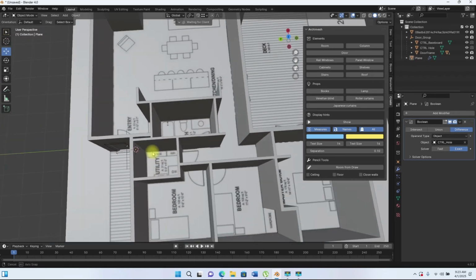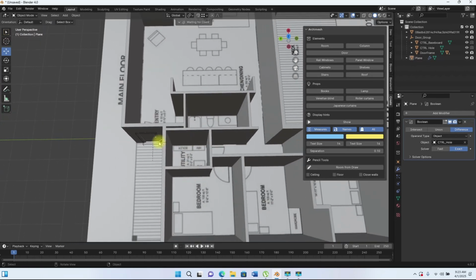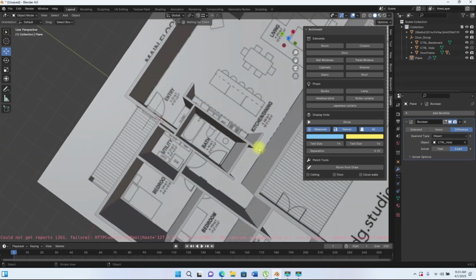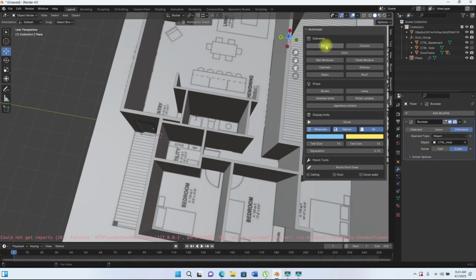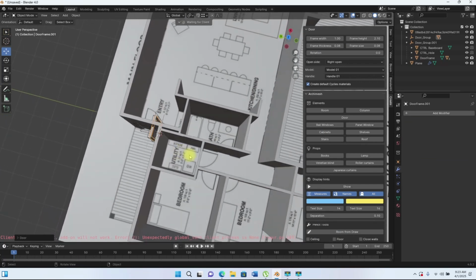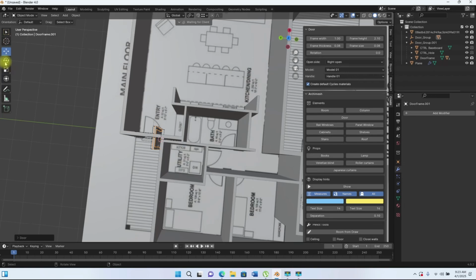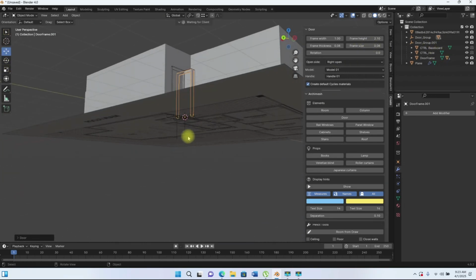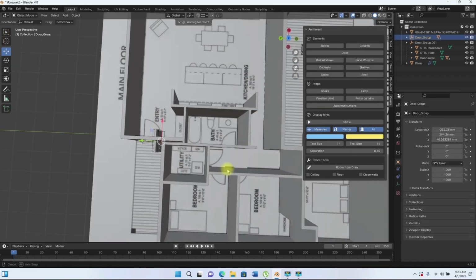All right. So let's do that. I will go back. So while nothing is selected, go back to the door, create another door. Another door is created. So let's just position this for this place. Use our move tool. Make sure this is selected.